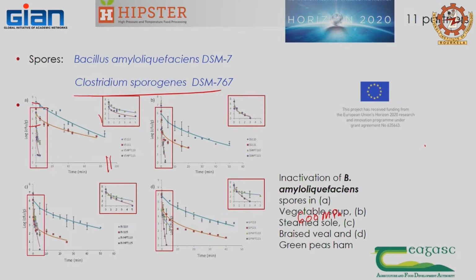Why was the limit set at 600 megapascals? Because if we go for 700 or 800, we can reduce the time even further, but the strength of the material becomes challenging. The design aspect here was that whatever vessel is used is preheated to a temperature, then it goes for high pressure. Otherwise, you have to heat up the whole vessel where we are generating the pressure.